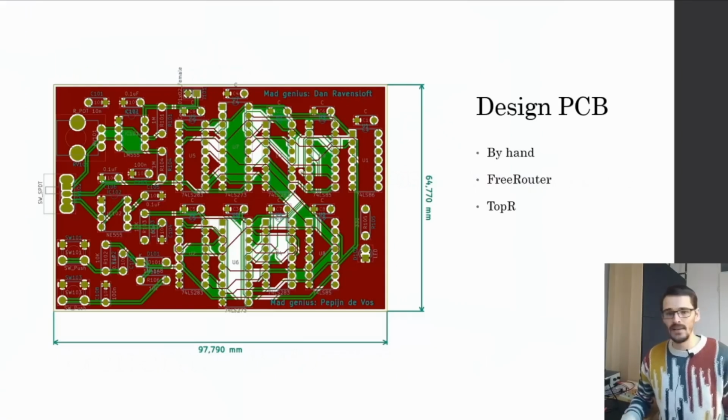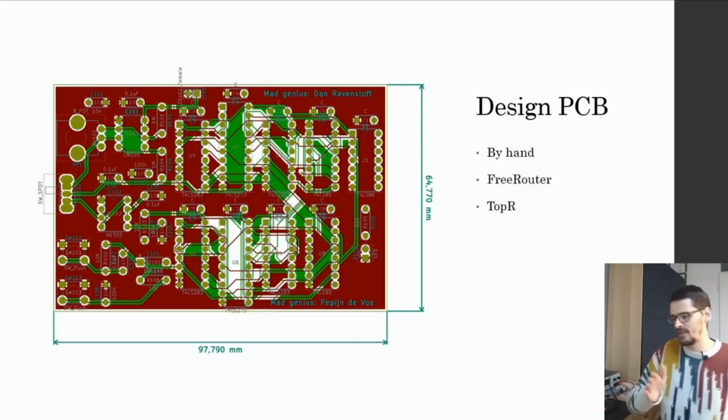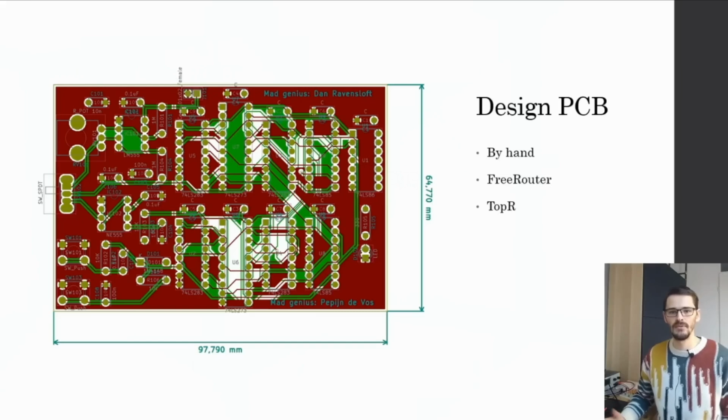And then finally you import it in PCBnew. So in this case the right hand of the circuit is just some 555 timers, for single stepping the logic and tweaking the speed of it. And then the left side is the generated netlist from Yosys.